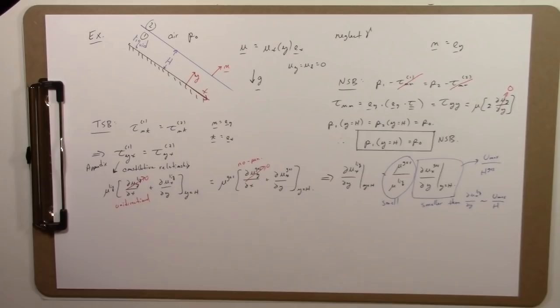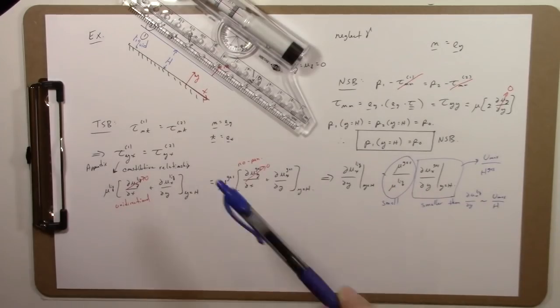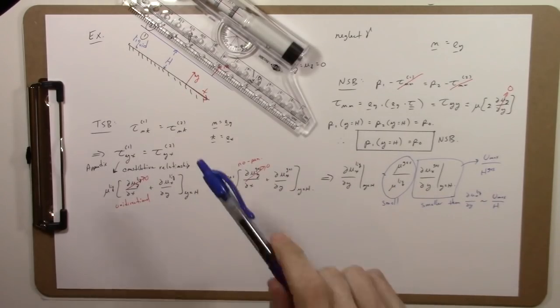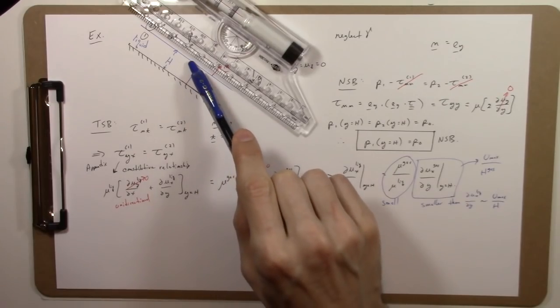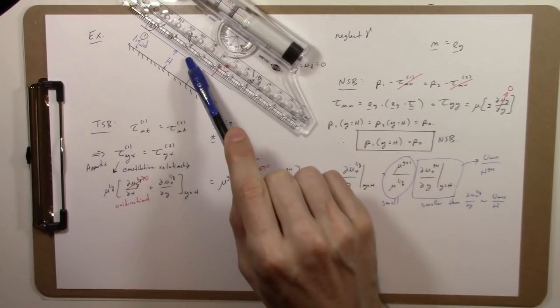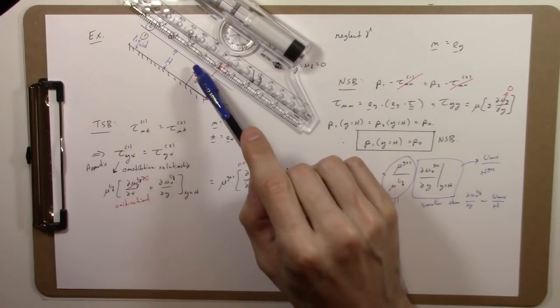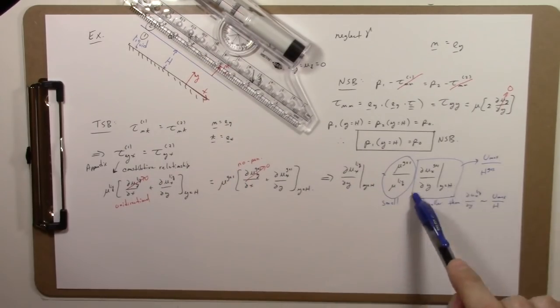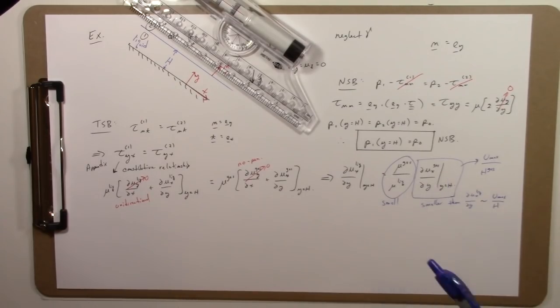So the only reason this wouldn't be true is if you had a very thin region of the gas. So say you had a bounding surface right like this. So you had a very thin region of gas next to the flowing liquid. Then the velocity gradient is going to be very large in the gas. It's going to go from the interfacial value, which is equal to the liquid value, because that's the no-slip condition, to 0 over a very thin distance. And because that velocity gradient is then so large, this term here would be relatively big, and relatively big times small means something that's important.